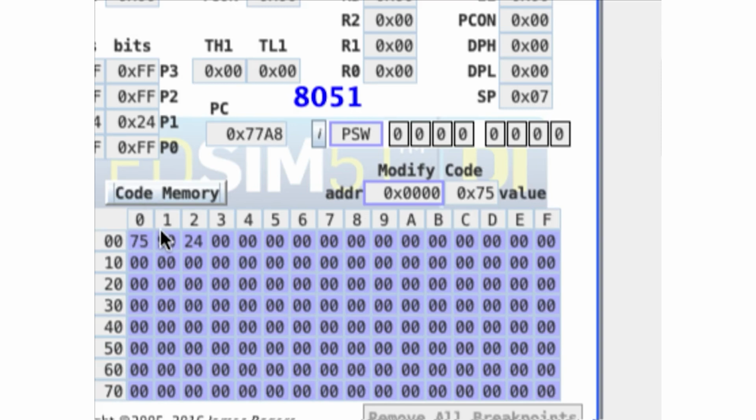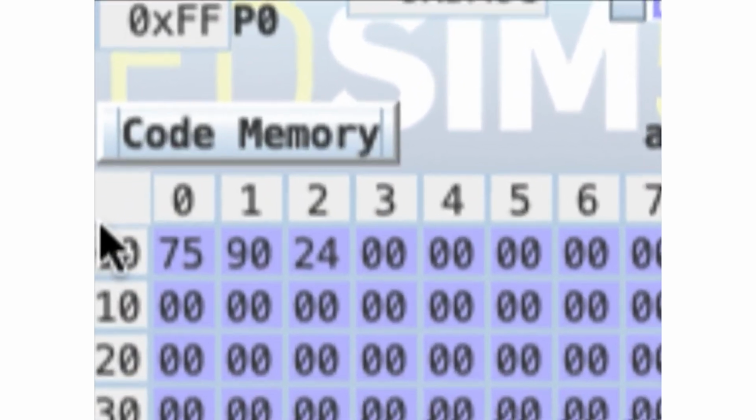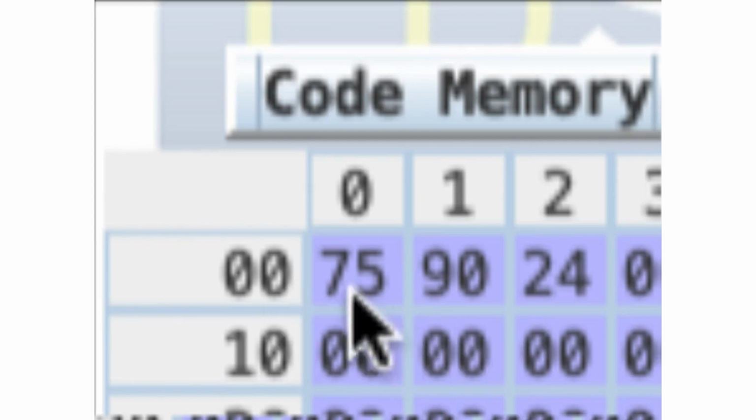You can probably guess what this means. So that's the high bit of the address, 00. Now, 0000, that would be the start of memory, right? So the instruction got translated to the top, right? And you remember we did a move of 90 hex to 24 hex? And if you stare at it, hey, that looks kind of familiar. I didn't recognize 75, but I recognized 90.